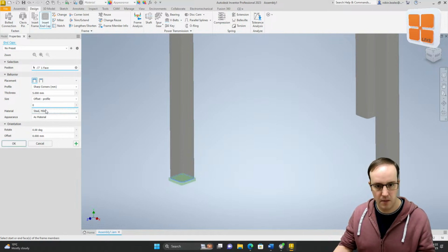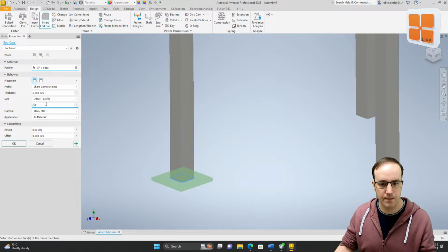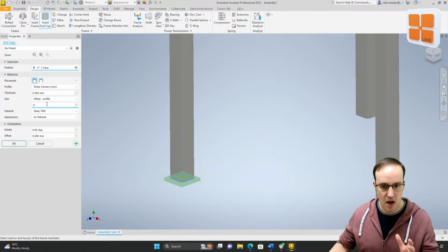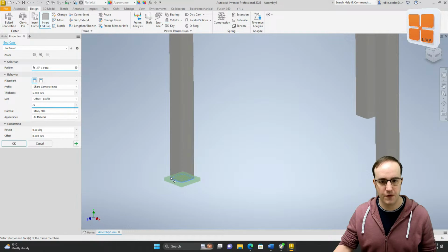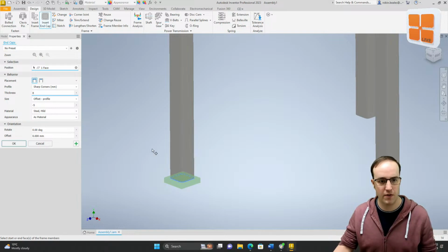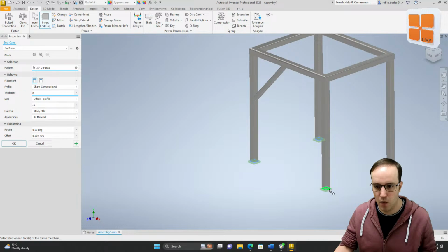Zero. And make these as big or as small as you want them. So I'm going to put in there a -5 size for those end caps, and then maybe they're going to act as feet. Maybe I'm going to have them up as 8mm, and I'd weld them on there, or something like that. I can add all of them at once and place them on like so.